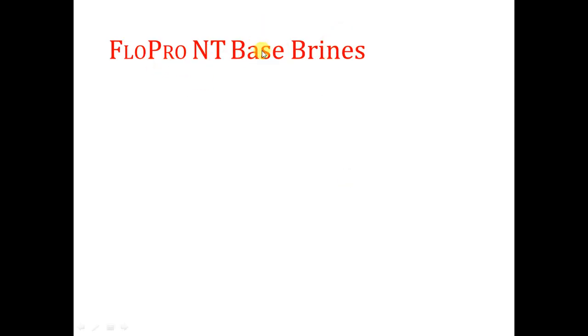The base brine. What are the brines that we use in the Flow Pro system? Actually, the Flow Pro system is the same as the solid free or low solid non-dispersed mud. So there are no solids or very little solids in the mud. So the first one, or the base fluid, is called here the base brines. What are the base brines?